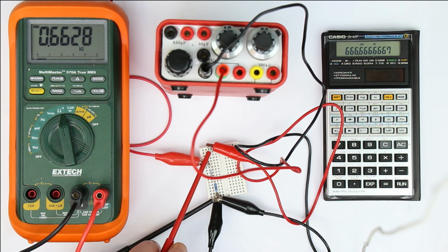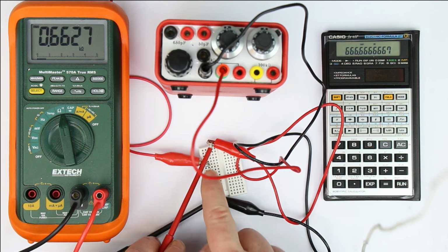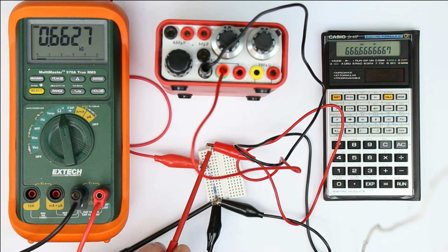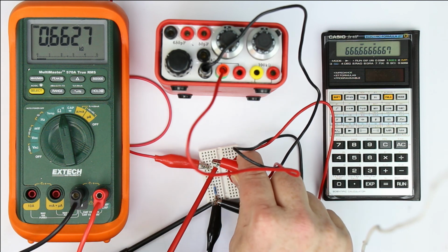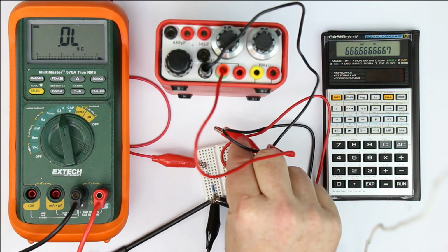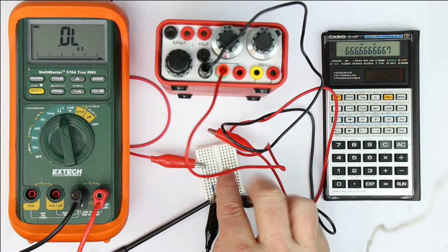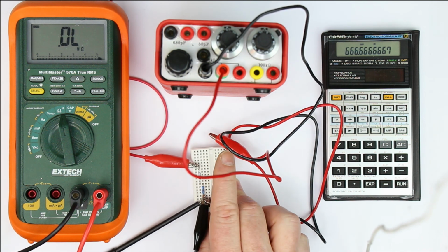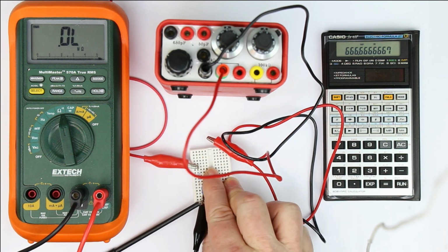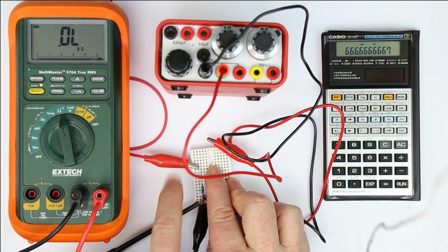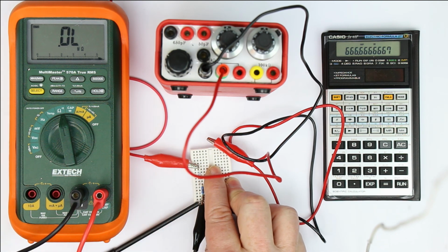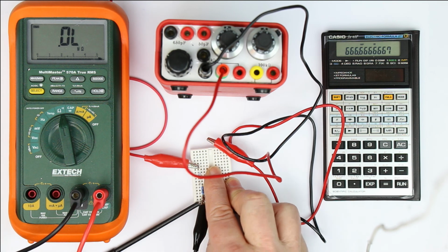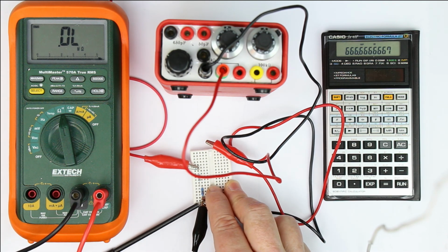The remaining difference are simply the tolerances of the resistors and the test setup, etc. But you could see again, with this method we can measure the true output impedance of any voltage source. However the internal wiring, if there's a divider or only a single resistor or whatever, we can measure this quite accurately, and it's a nice and quick way to determine the output impedance of an output of a signal source.